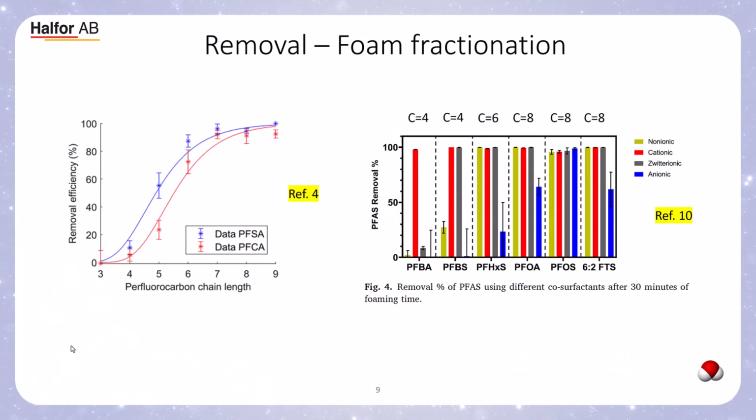How does foam fractionation remove PFAS? First, I think you need to state that it's very dependent on the water matrices from the beginning. Then we need to split the question in two parts: if we are not using surfactants, or if we are using surfactants. Those two situations are very important for how good the removal of the PFAS in the water is.